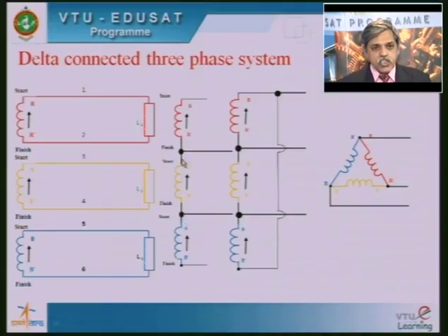So these two junctions are there, and I just took two wires here. That means conductors 2 and 3 are replaced by a single conductor, and 4 and 5 are also replaced by a single conductor, eliminating two conductors out of the six.